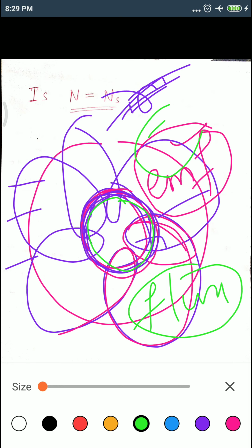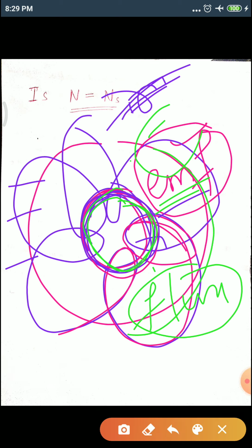Due to this, relative motion between the rotor and the stator is going to happen, and then the entire set of rotor conductors experiences a force. Then the rotor experiences a torque, and the rotor starts rotating. This is the cause of it. The RMF has to move, and a conductor linking with the flux is going to produce EMF in it.